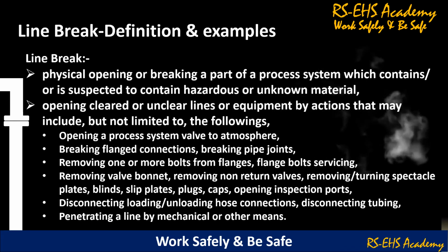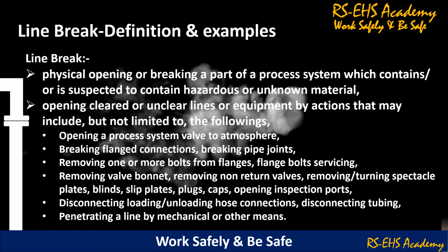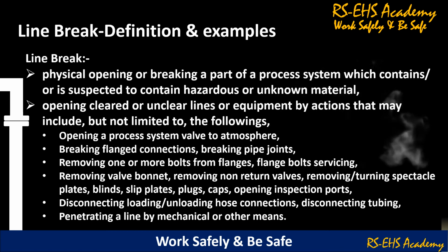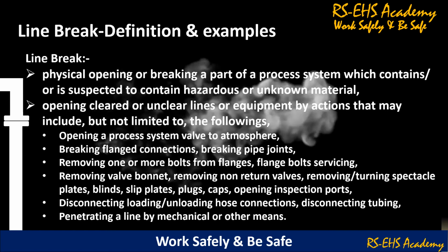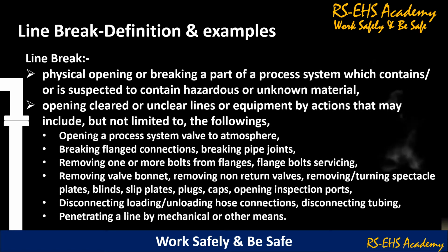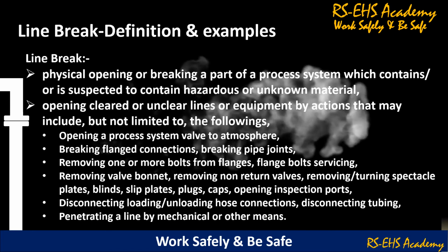flange bolt servicing, removing valve bonnet, removing non-return valves, removing or turning spectacles, plates, blinds, slip plates, plugs, caps, opening inspection ports, disconnecting, loading or unloading hose connections, disconnecting instrument tubing, penetrating a line by mechanical or other means.